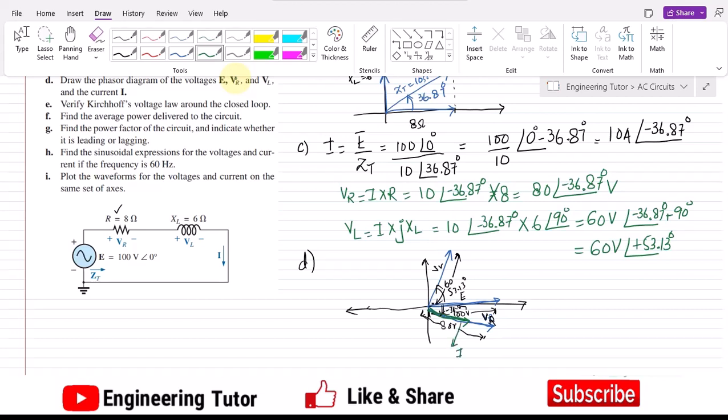In the resistor you may very easily see that the current is in phase with the voltage. But in the inductor you can see that the voltage is here while the current is 90 degrees away from it. Similarly we can see that the voltage is leading because it has achieved the positive angle as compared to that of the current.